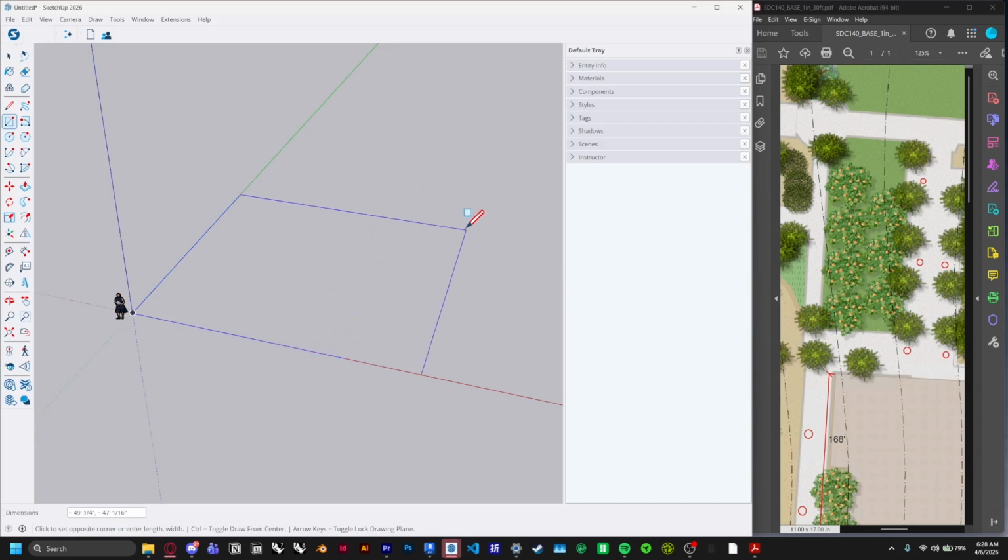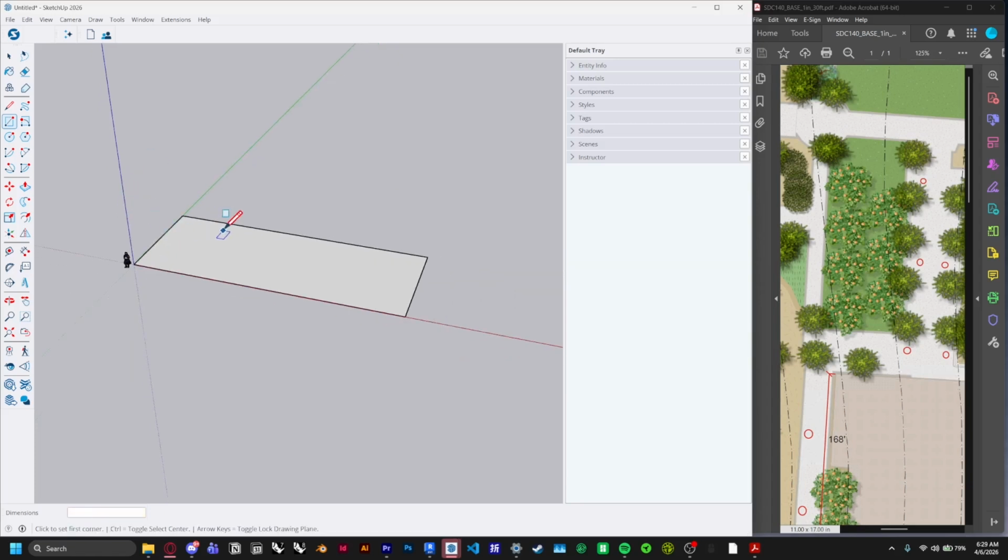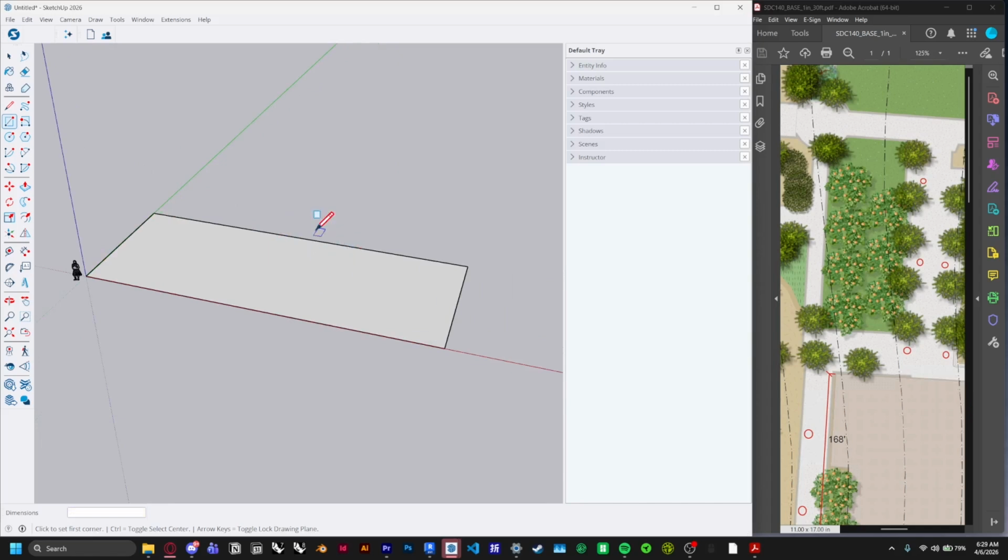The cool thing is you don't need to click the box down here, you can just start typing. So, I have my mouse out here, and then 81 feet. So 81 and then apostrophe and then comma to separate the two distances. And then 32 feet. So it does look like it rotated, or I inputted the distances incorrectly. They should have been flipped.